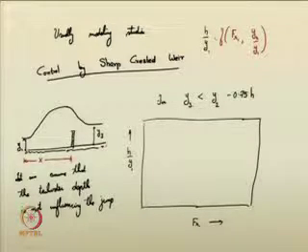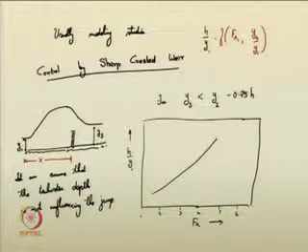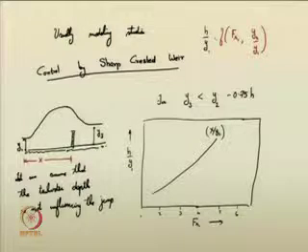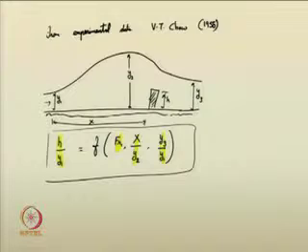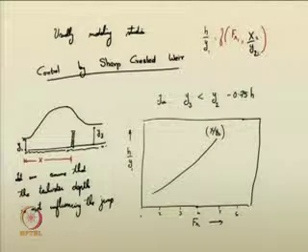Following curves, say Froude number may be 1, 2, 3, 4, 5, 6 like that. So, we can have various curves for different values of x by y2. We can have various values for x by y2 as suggested here. So, x by y2 is the relation. For the sharp crested weir, h by y1 is a function of Fr1 and x by y2. Therefore, this is one particular curve.